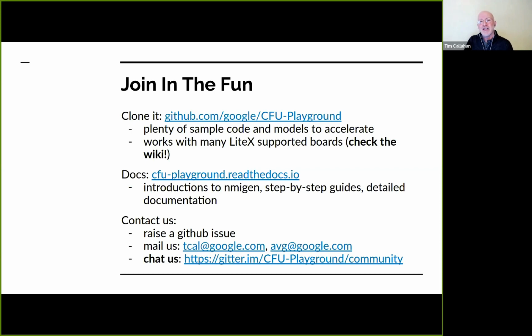So this is where the reality of hardware design comes in. If you throw too much stuff into your CFU in one combinational path, you will have difficulty meeting timing. And then you're doing this back and forth of balancing the hardware that you build, inserting registers to break it into cycles to keep your clock rate high. So that's where you will have to recognize that you're building hardware.